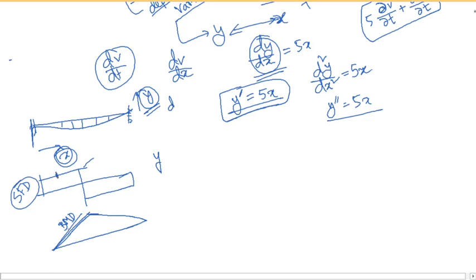Say for example, for this one, throughout these points, the bending moment, you see, is a straight line. That's why the slope of these points is constant, and that's why the shear force value is also constant. So we can say the moment's derivative with respect to x is proportional to the shear force, or we can say V, instead of SF.